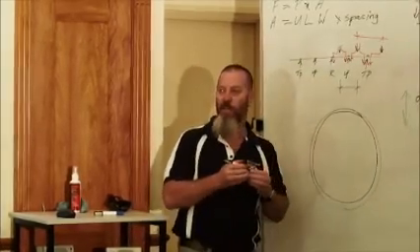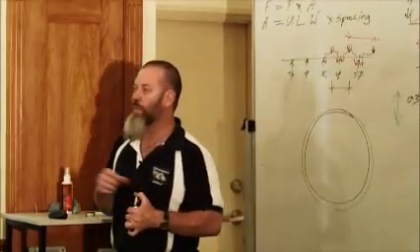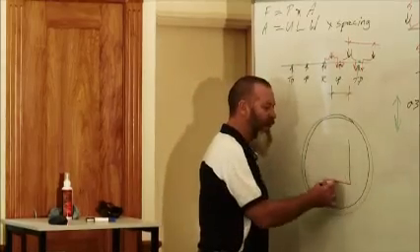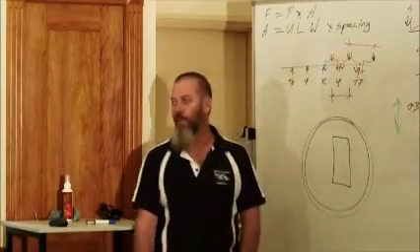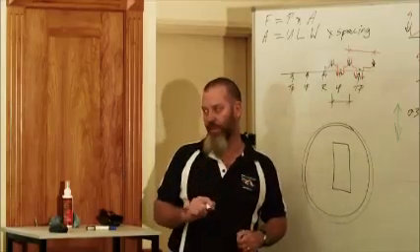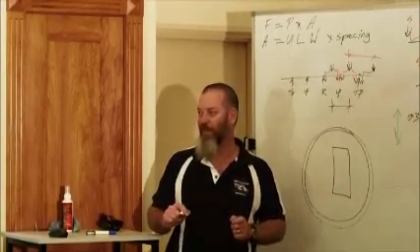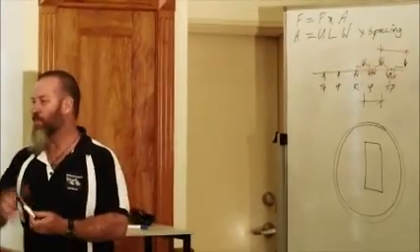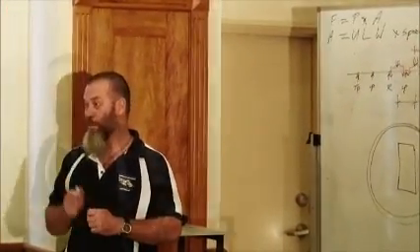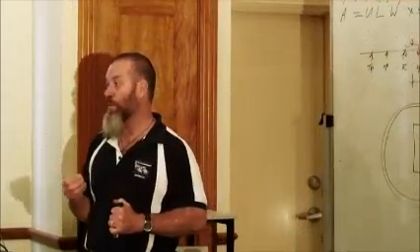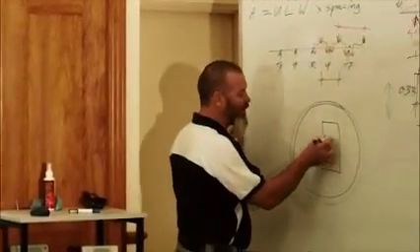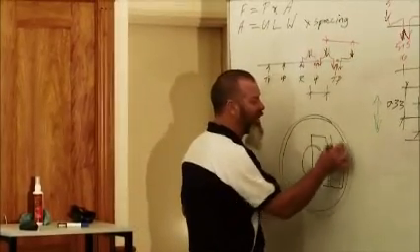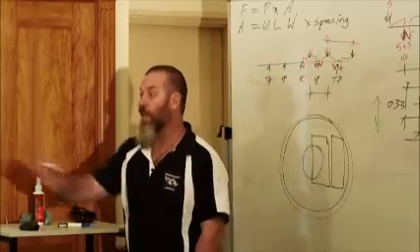So the moment when you get a piece of treated hardwood, the treated hardwood is what we call an envelope treatment. It's just basically a treatment that goes around the outside of it, because it's likely that the piece of hardwood that you're using comes from there, which is all heartwood, which doesn't accept treatment. So providing you don't cut that piece of hardwood, your treatment's all good. And that rarely happens. And that's why we use treated pine quite a bit, because a treated pine log, this section here will have heart in it, so it's not treated correctly. But if we can get a section from out here, that's treated correctly, and you can cut that and it's no problems.